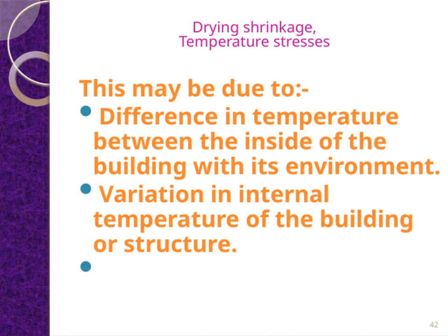Different areas might experience different temperatures, especially if there are poor insulation or heating issues, leading to uneven stresses in the structure. We also need to consider drying shrinkage, which occurs as materials like concrete or wood lose moisture and contract. This process can cause dimensional changes and potential cracking if not properly managed.